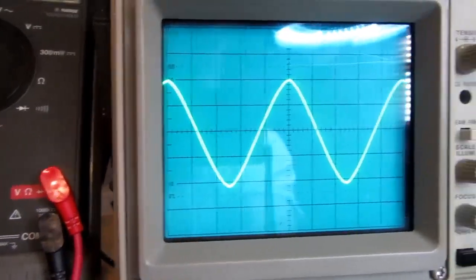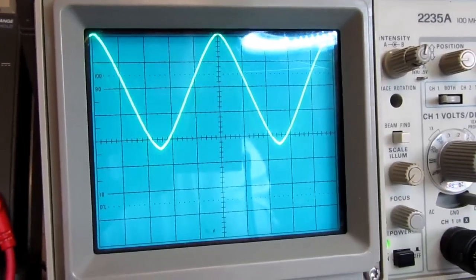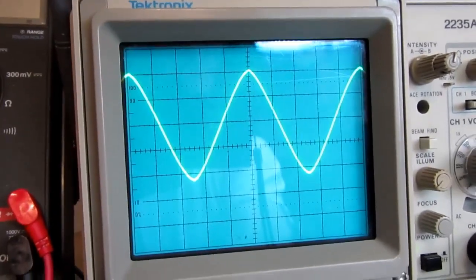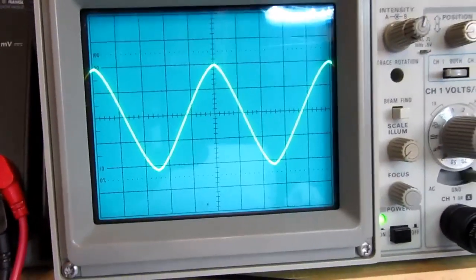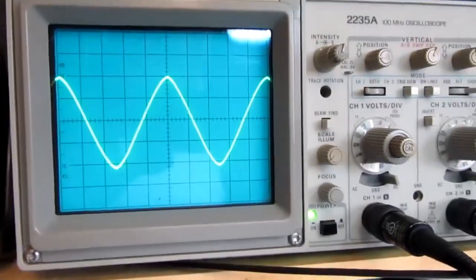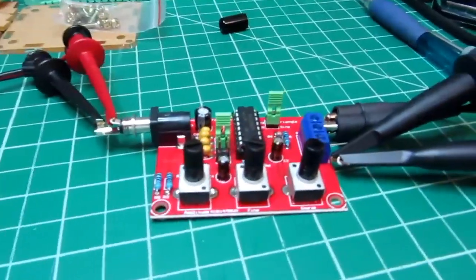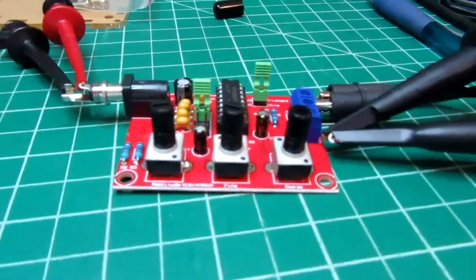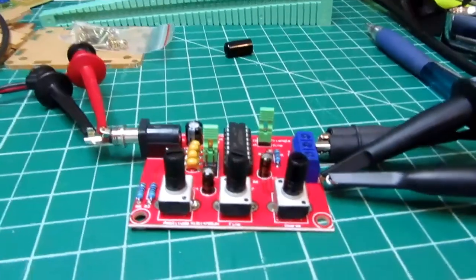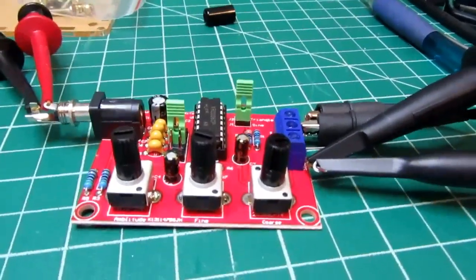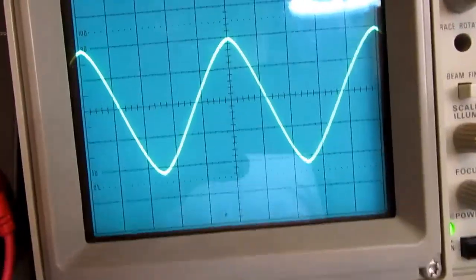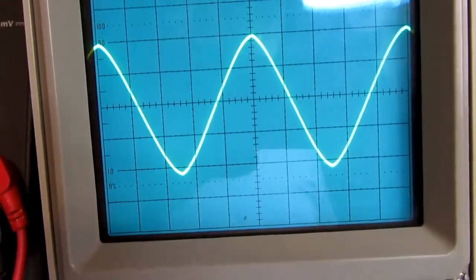Does it get any better if I go up towards 12 volts? No, the waveform does not improve. So it's perfectly good at 9 volts, as far as perfect can be considered with this thing. This thing's kind of a piece of crap, actually. I'm very disappointed in it. I'm not sure what they did wrong with this design, because I thought this IC could do a better job of that. That's not a sine wave. That's a messed-with triangular wave.